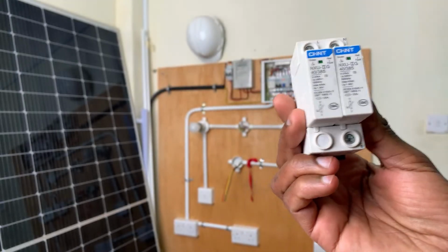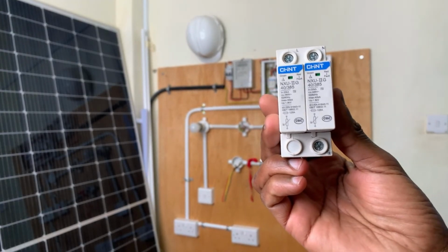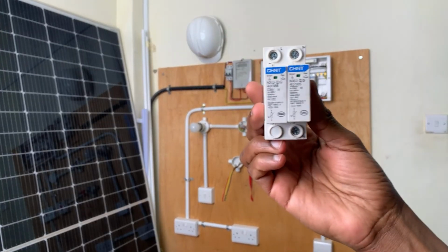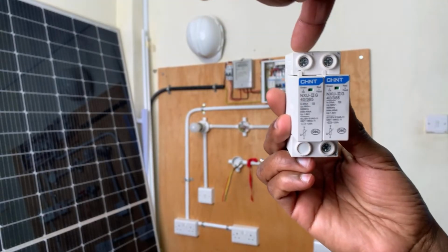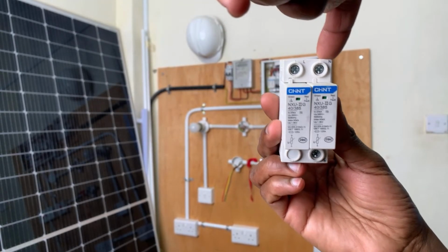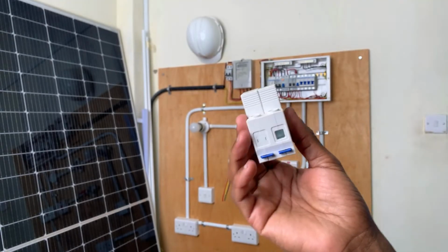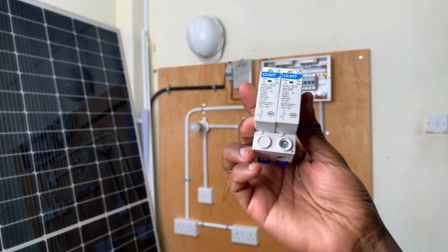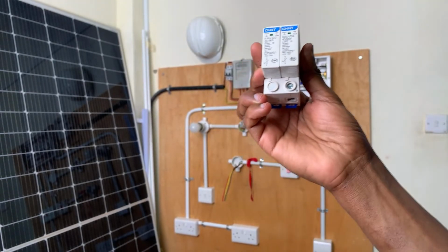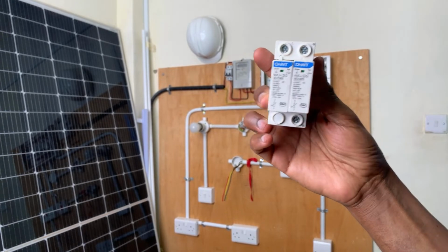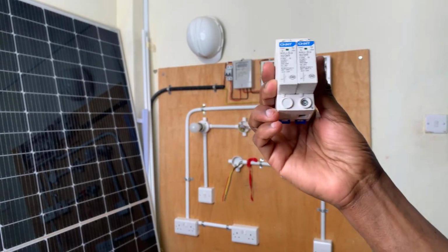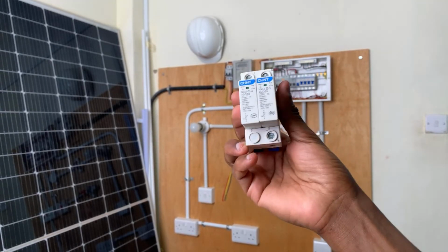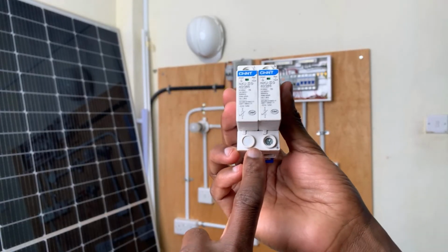Right? So this is an SPD, a surge protective device. Now, what you see here is we have the L, the line or the live connection. We have the N, or the neutral connection. And then at the bottom section, we have the earthing connection. Why is that important? Its purpose is to detect any surges that are in that line and neutral, and then dissipate them directly to the earth using this termination that is below here.